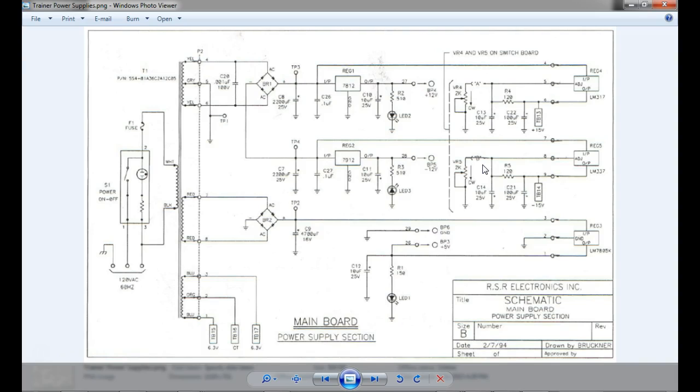This is a multi-winding transformer, right? Okay, and that's it, guys. So there they are. The LM317, this is the variable positive regulator. The LM337, that's a negative variable regulator. Here's our feedback resistor. There's that circuit that I showed you. We have unregulated in, we have regulated out, we have our adjustment. Are you okay? These are all fixed. These are variable regulators.